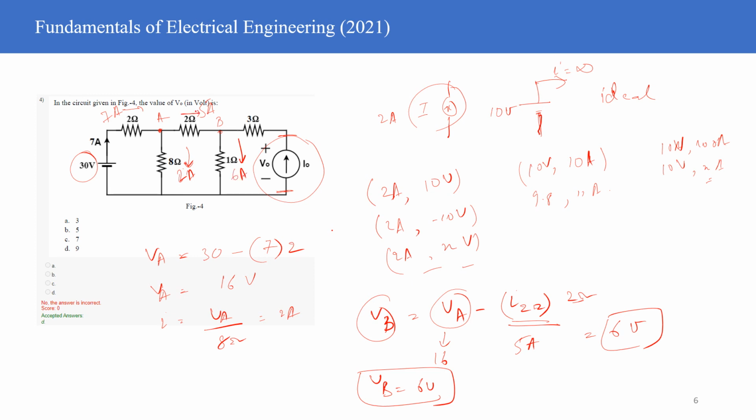So the incoming current is 5 ampere, the outgoing current here is 6 ampere, therefore there must be some other incoming current of 1 ampere magnitude, right? Right guys? Because the KCL must be followed, right? So at this node, you can write the KCL. So 5 ampere current is coming in, 6 ampere current is going out, therefore 1 ampere current must be coming in. So that must be the value of I naught, because that is the value of current which is coming in.